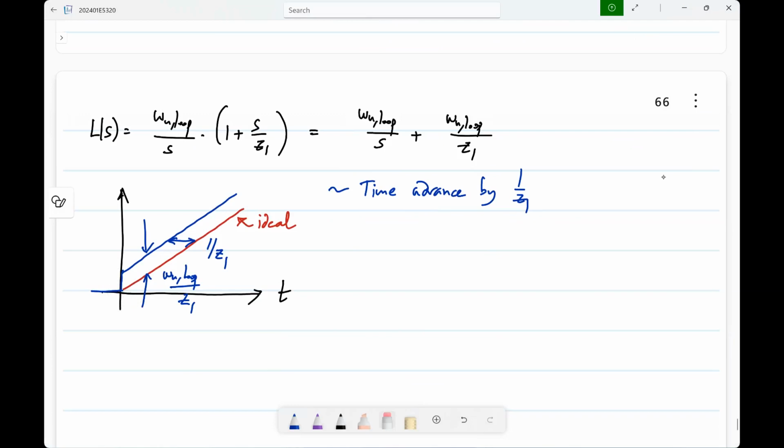So let's say you have a lot of delay, and possibly if you introduce a 0 somewhere in the loop, you could advance the step response and improve the stability. Is this okay? So this time domain reasoning is also important. The reason I like this is, first of all, this integrator model brings in the idea that you are continuously adjusting the output until the error goes to 0. That's what the negative feedback loop is doing.